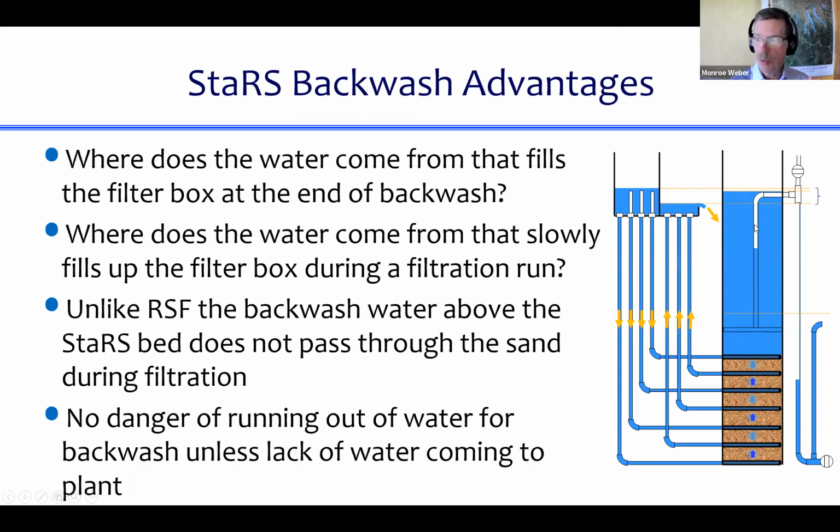So the water that's above the filter in a STARS filter never gets filtered. It gets dumped. So it's both a good thing and a bad thing. It's good that we're not filtering that because it's dirtier water. It's bad in that we end up dumping a fair amount of water to make this transition between filtration mode and backwash mode.